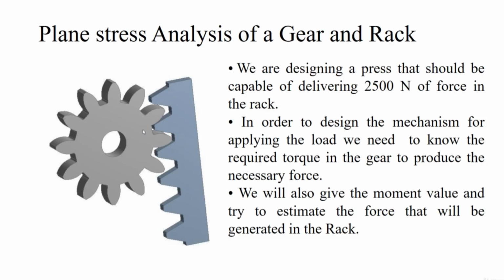Coming to the second case, instead of giving the force here, we will fix this particular position and then apply some moment value and try to find out what force value is generated for the moment that has been applied here. We are going to perform all of these things in ANSYS Workbench, and we are going to simplify this geometry and perform the analysis in 2 dimensions.